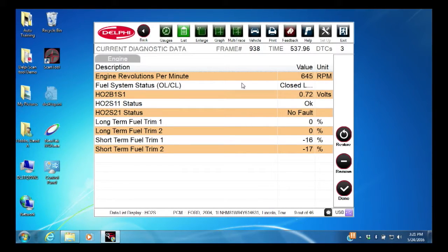It's essential to look at the cells as we drive the vehicle to see which cells of drivability, high RPM, high load, or lower RPM, lower load, are good information sources for you to determine, do we have vacuum leaks, do we have fuel pressure issues, fuel delivery issues.